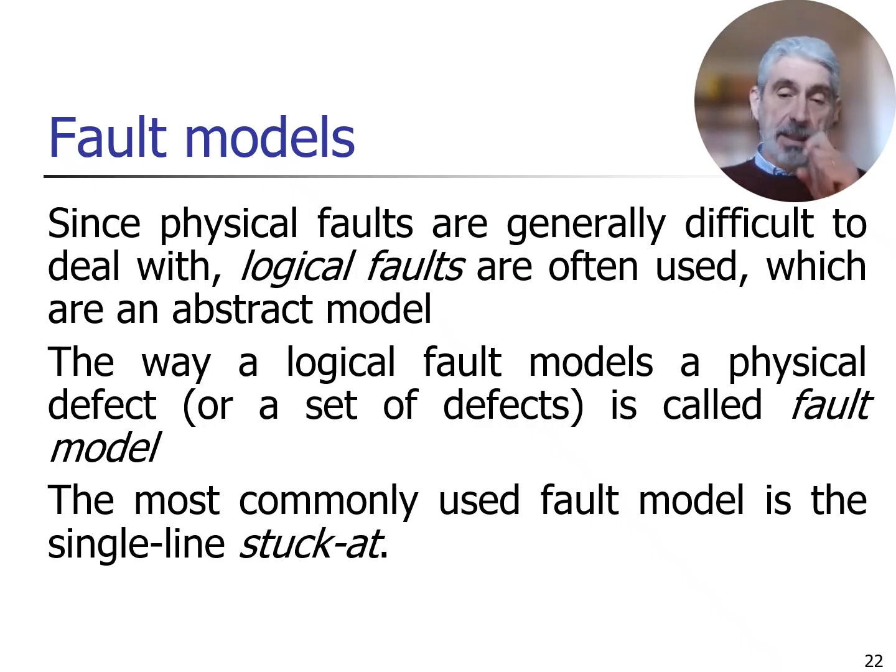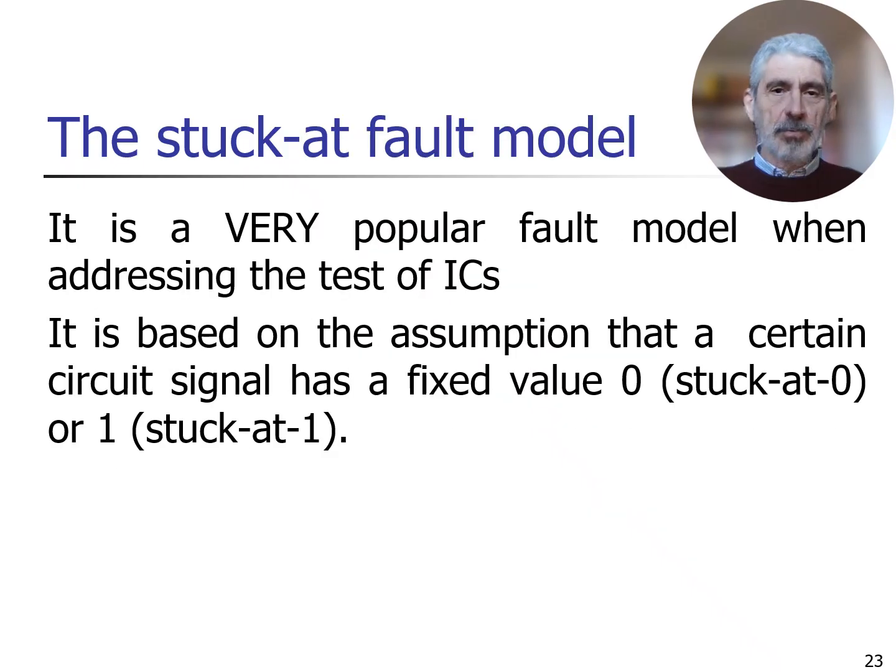The fault model is a representation of the possible defects, easier to deal with, easier to manage, and allowing the test to become simpler and more effective. The most commonly adopted fault model for digital circuits is the stuck-at fault model that we will consider now.